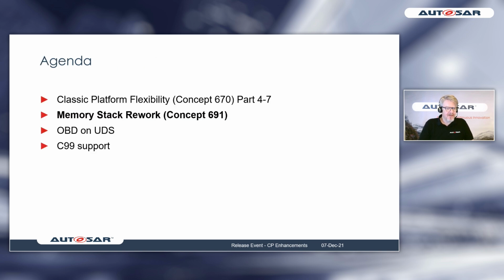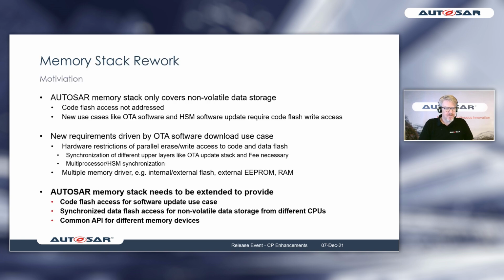But coming to the next topic, memory stack rework. This is also a very huge topic because currently in AUTOSAR, or in the past, AUTOSAR concentrated on non-volatile data storage, so that I can, from a software component, store my local data in non-volatile memory. But more and more use cases are coming up in the market, which also require additional needs. So for example, the over-the-air update, so that I need to be able to address the code flash also in application software, to write to a B partition, for example.